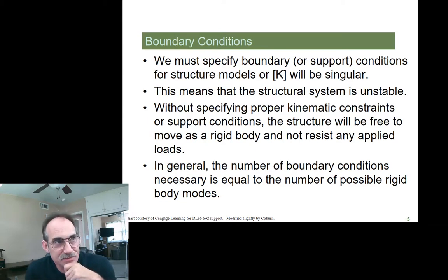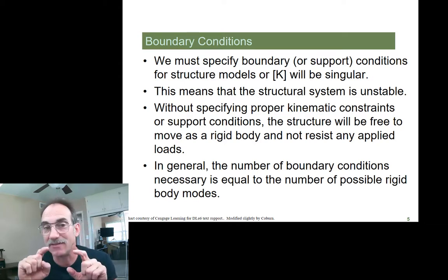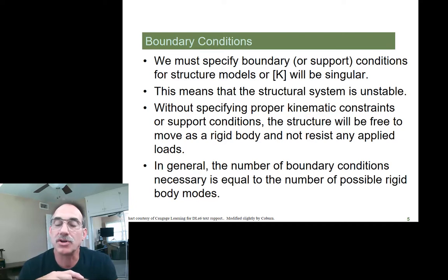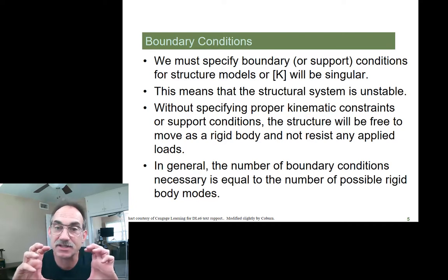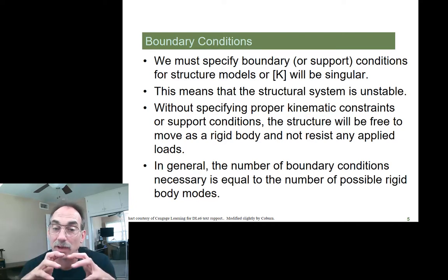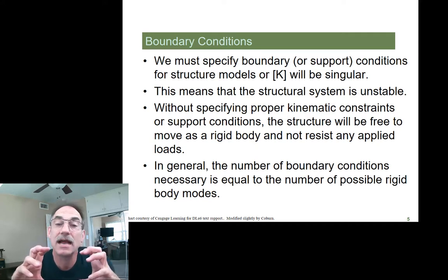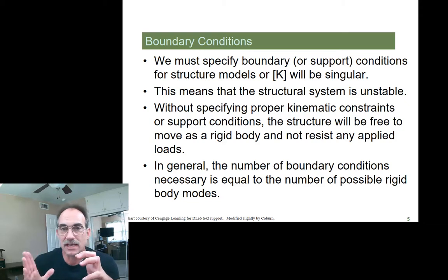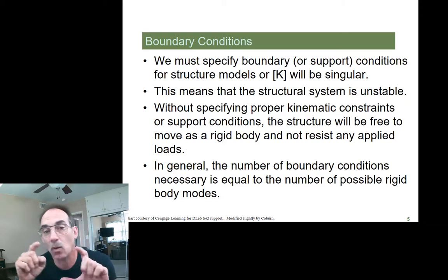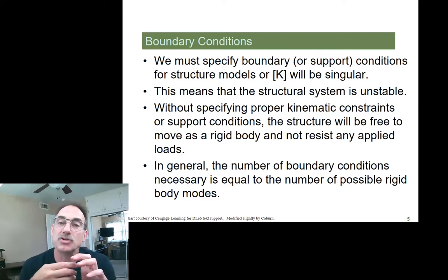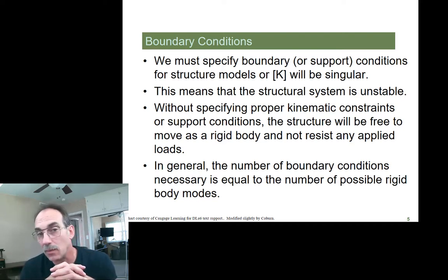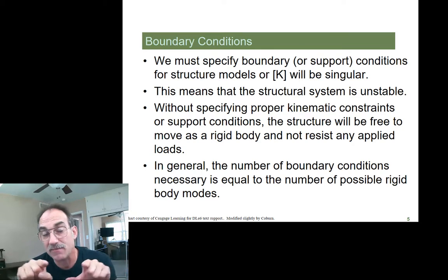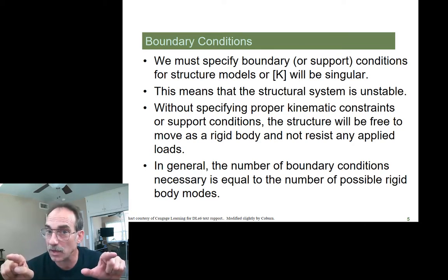We're going to have to not only calculate the stiffness matrix of each and every element, we're also going to have to then assemble the stiffness matrices of all the elements into a global stiffness matrix. And then we're going to be relating forces to displacements as a function of these stiffnesses. And in order to solve these, we're going to need to impose our boundary conditions, just like we did when we were calculating the deflection of beams in AERO 3261.